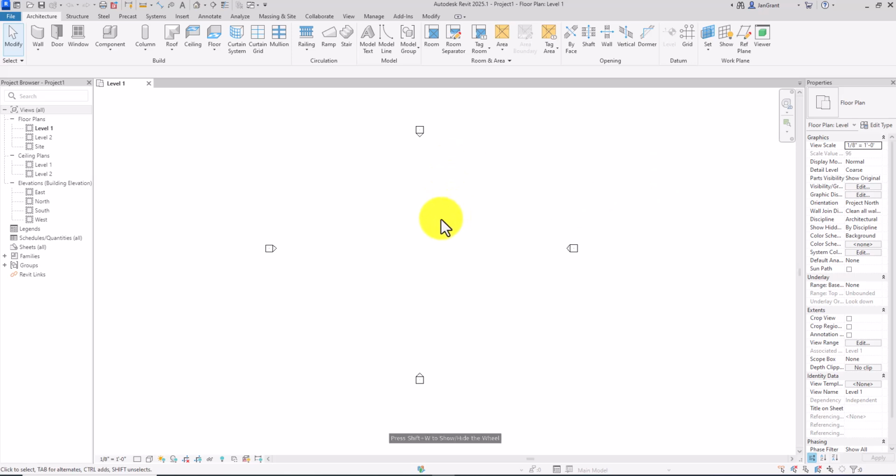I won't mention that again because I just wanted to point out a few things in this beginning class. You'll see all these icons that are kind of clear on what they do. And I want to point out to you that these boxes with triangles will establish the view of your elevations. So we're creating one model, and from that one model, we're going to be able to see these different views over here in the project browser. So once we establish a building, all of these are pointing towards your elevations, and that's where these are right here. All right, so let's get started.